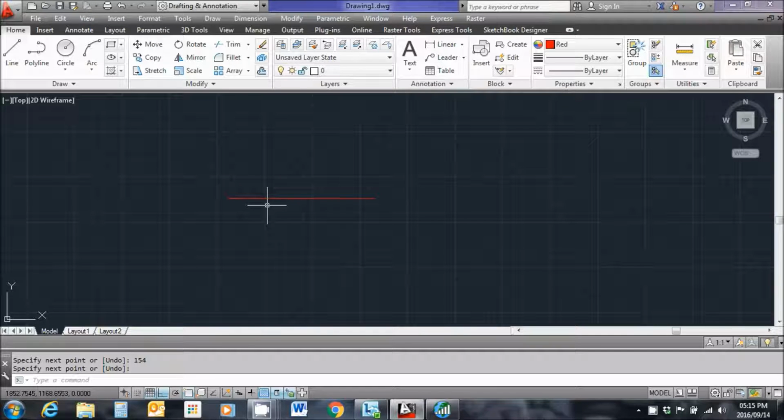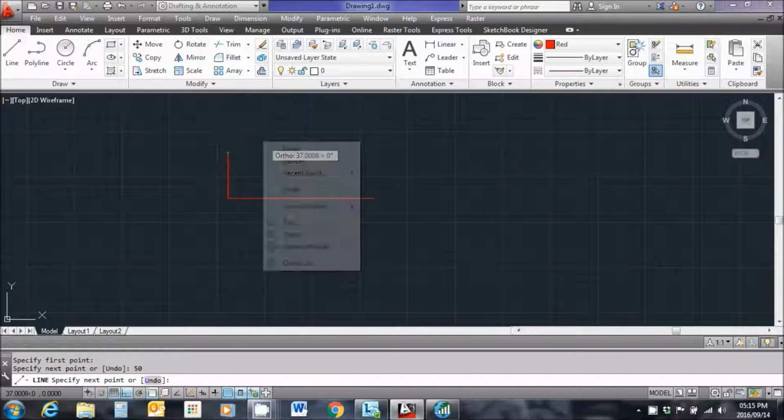Right, so I'm going to draw in a vertical axis that is 10 meters long. In order to do that, I have to multiply 10 by 5, so I'm going to get 50 drawing units. So let me go ahead and draw that. Vertically up, 50 units. And there I have it over there.